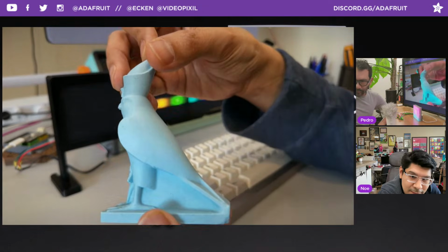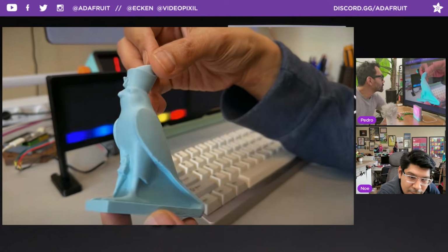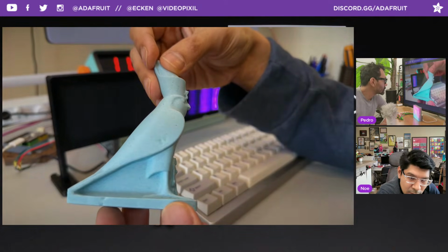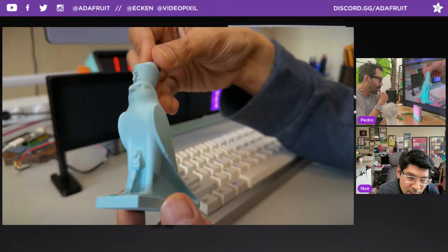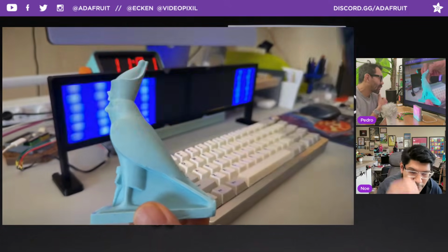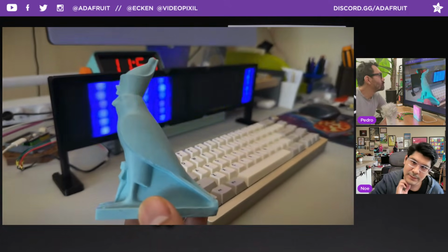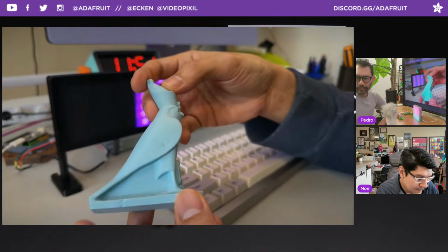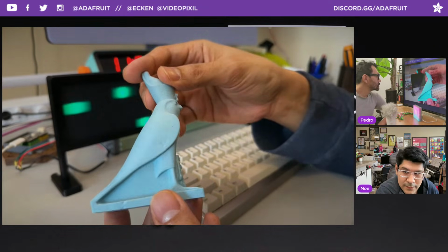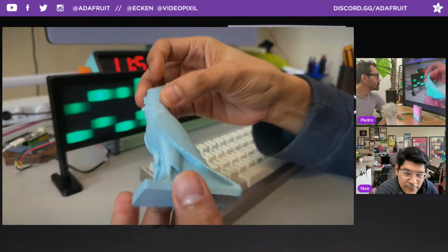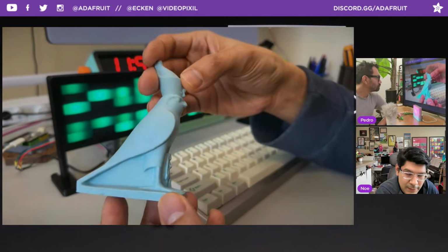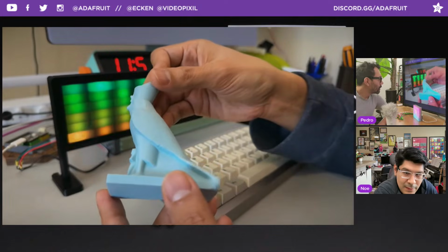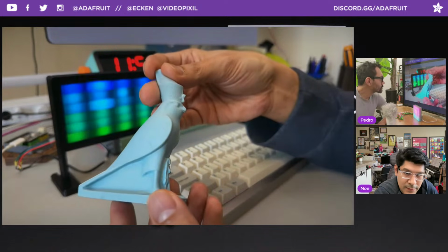It's very detailed. I think when I converted the USDZ to an OBJ file, an object file, it reduced the polygon count for me automatically, which is nice. But if you have something like Blender, it could be more granular with how much you want to reduce the polygon count. You don't want it to be too high because then you won't be able to print it. Your slicer can't handle it. So there's all these little things that you can do to it.